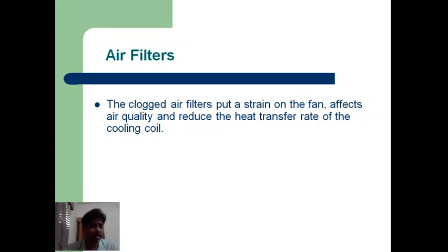It is advisable to clean the air filters once in 15 days. I even suggest you clean the air filter once a week. While you are running the AC, you must clean the air filters once a week. In this way you can save a lot of energy.